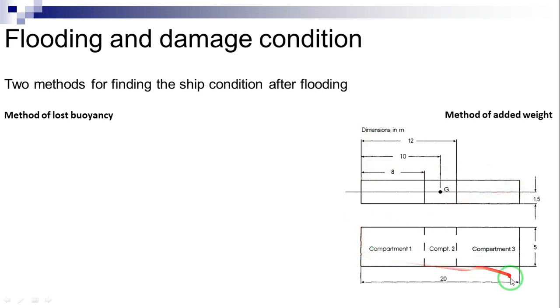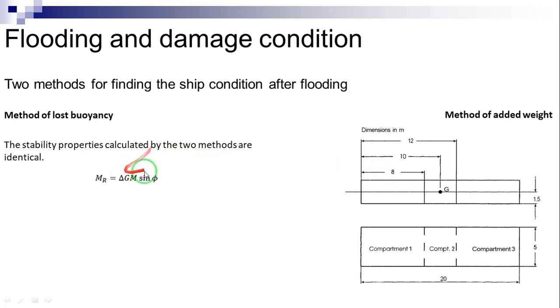If we compare the initial righting moments, the term initial has the meaning where we consider initial stability as a property governing the behavior of the floating body in a small heel range around the upright position. In that range, the righting moment equals this equation. As we are going to see, we obtain by the two methods the same righting moment.